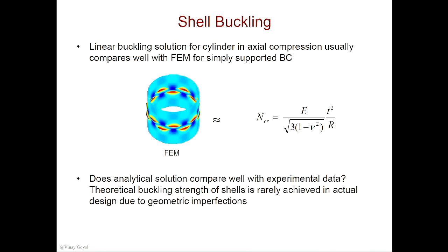But the problem is, as you can see from the mode shapes here, they tend to be shell modes. They're very localized. Let's take the ruler, for example. That first mode is not local. It's not like a little bump on the ruler, right? It's a first mode that's quite visible there. For a shell, though, the imperfections tend to be local to the wall. And so they tend to be small imperfections in the wall or small mode shapes in the wall.